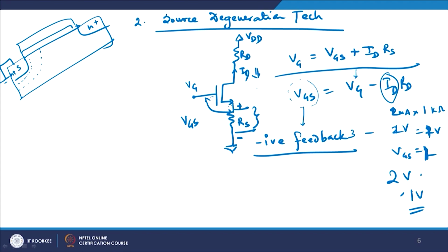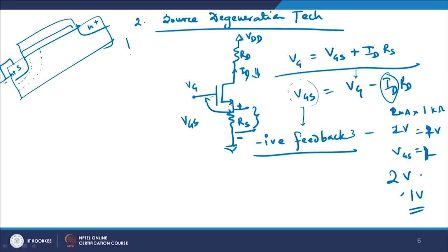So what happened, you increased the current, and the decrease in VGS forced the current to go down. If you plot ID versus VDS, your current increased. So what happened was, your VGS was large, you had a large ID, you forced the VGS to go low, and it forces the current to go low here, and so the current becomes something like this.